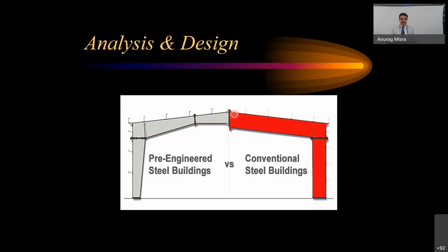Whereas in pre-engineered structures we are not using rolled steel sections, we are using all plates. So you could actually design a tapering section. I showed you in the metro station, it was a kind of curved section, a curved eye section, you can say.